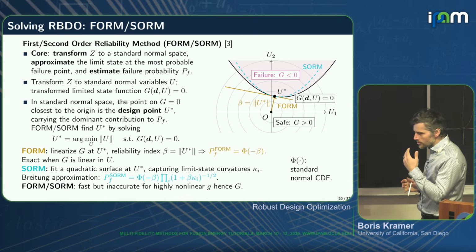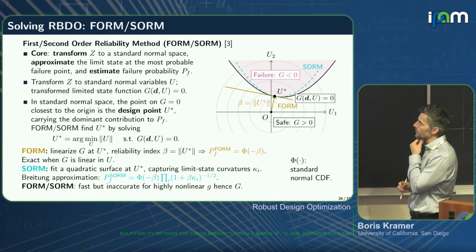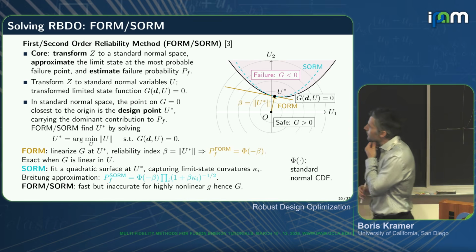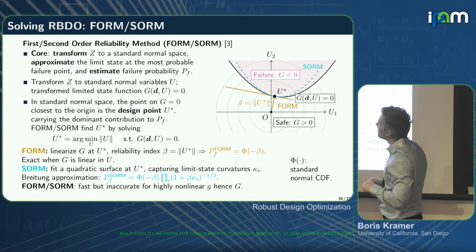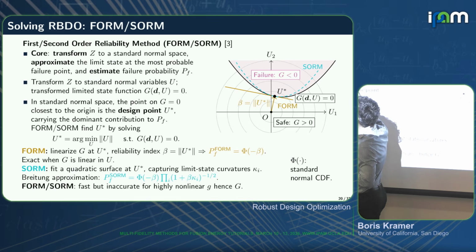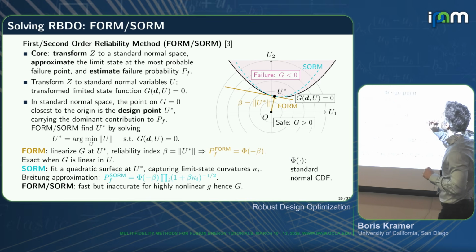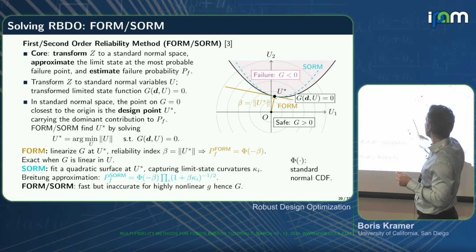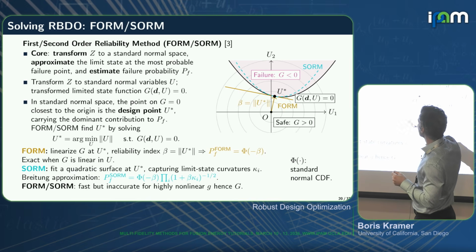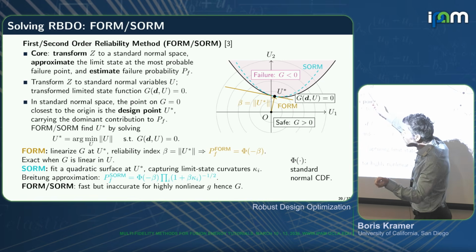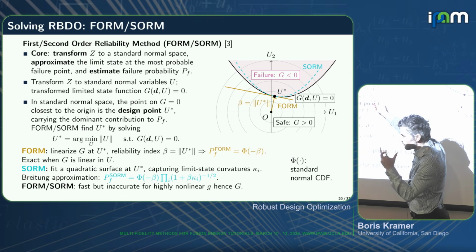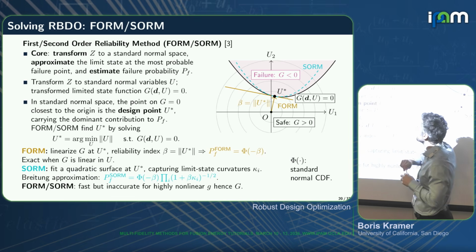But they call them also, very popularly, first-order reliability methods and second-order reliability methods. And the idea is once again relying on a change of measure. So you have your original random variable z, and you do a transformation to get into standard normal space, which is this one with the radial coordinates, the radial limit sets. And then in this standard normal space, you have to transform your original lowercase g into the uppercase G, the transformed failure region.